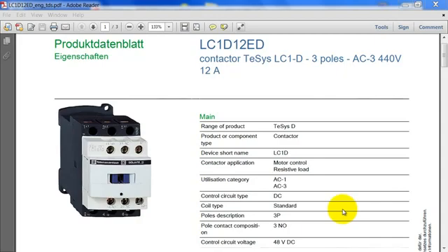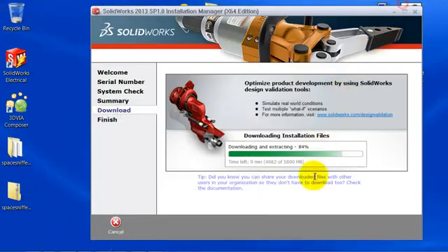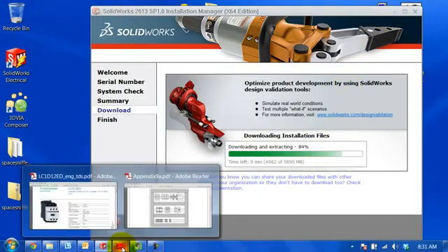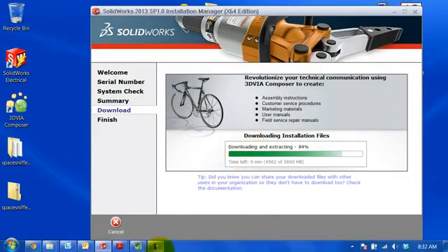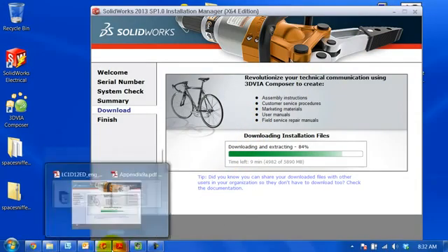Now, why do you want to use a 2D footprint? They're mostly used in cabinet layouts or 2D cabinet layout designs. So if I just show you an example, as you can see over here, if you don't have the 3D environment of SolidWorks and you're only using the 2D electrical environment, you can still create a layout of your cabinet like so. Our aim is to create one of those 2D footprint symbols ourselves. So let's go ahead and go into SolidWorks Electrical.